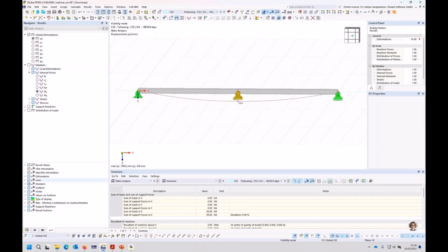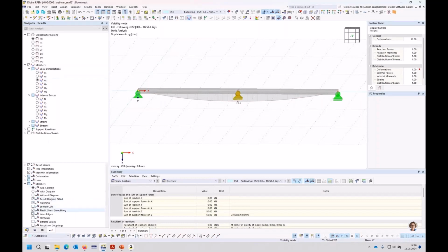It is a little bit visible that the deformation changes in the area of the start and end. When I look at the complete results of the deflection, it's recognizable that in this area of the beginning and the end, there is a changing of the deflection due to creeping. But what is more interesting is that there is a redistribution. I now calculated the structure with default settings.